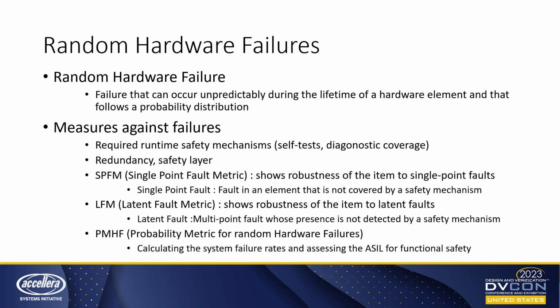It shows how this device can detect the possible failures, with the diagnostic coverage, and from this information we can get failure rates, and based on this information we can have a PMHF for each ASIL level.